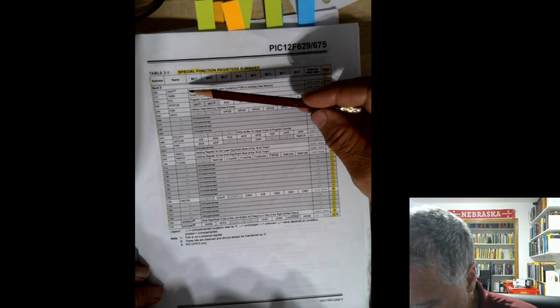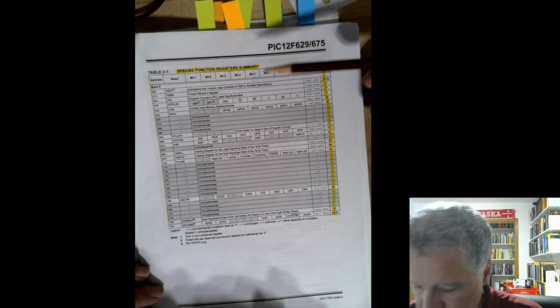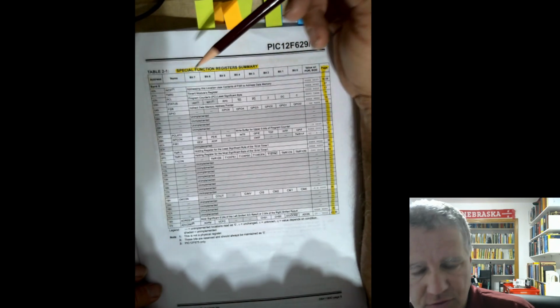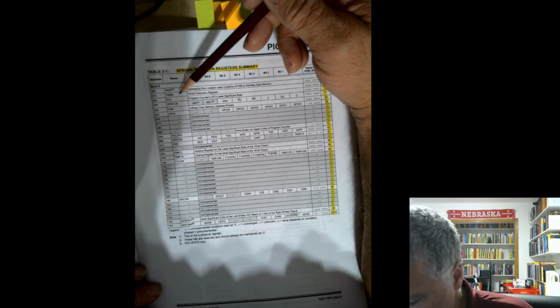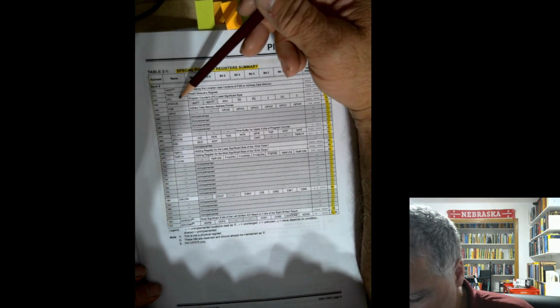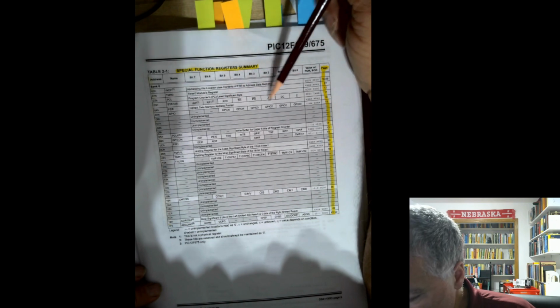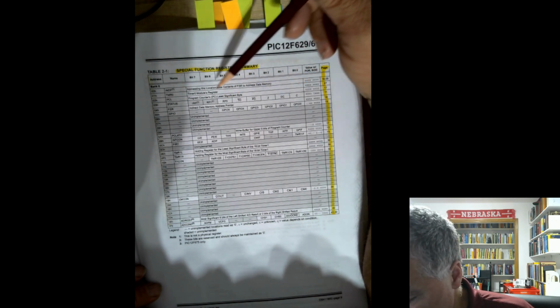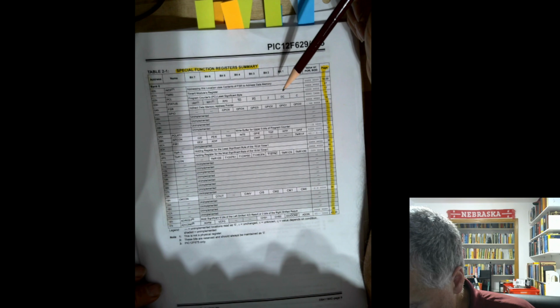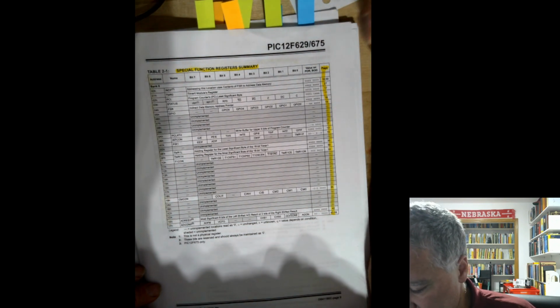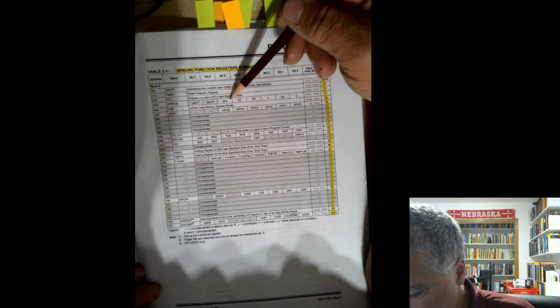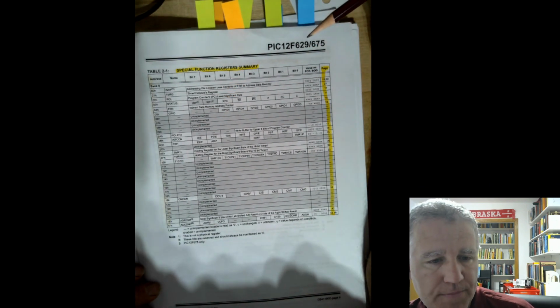Okay, so let's summarize some of the important registers. So the INDF register, that is for indirect file reading. The program counter is the PCL register. Status, this gives us a lot of flags. So when we're doing arithmetic, for example, our digit carry. Also, this RP0 is what bank we're on. So that's how we change from bank to bank right here.